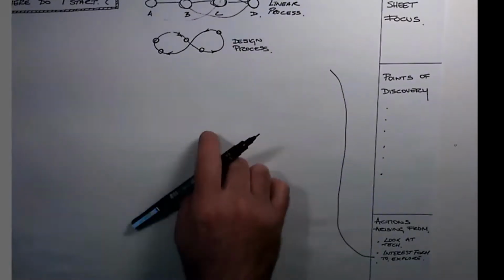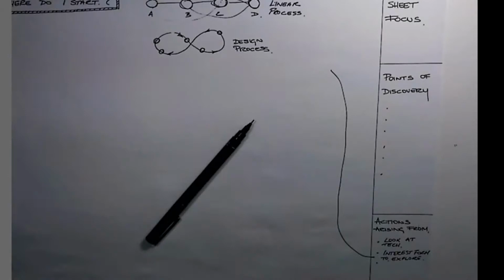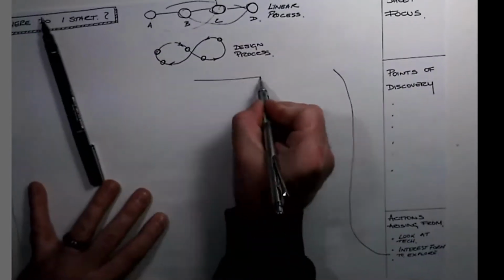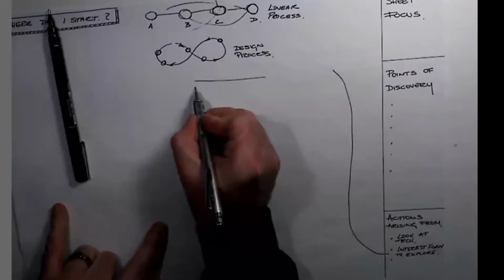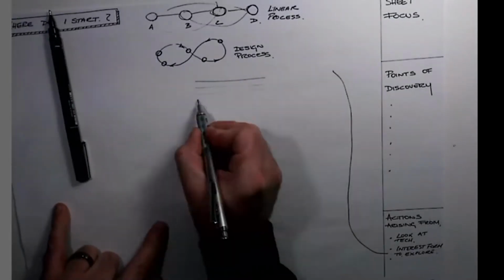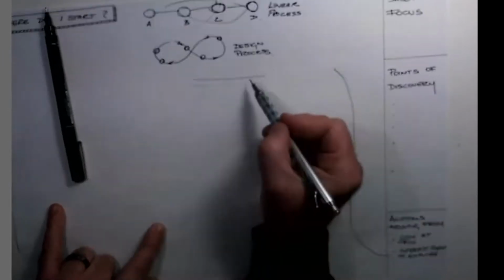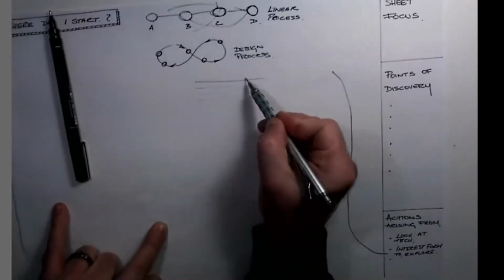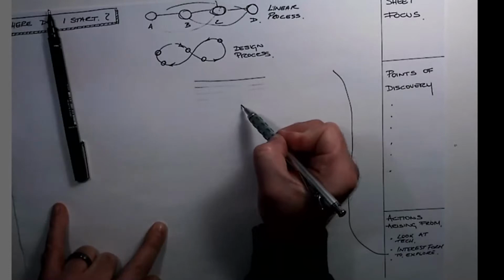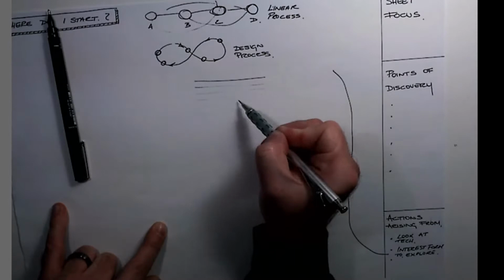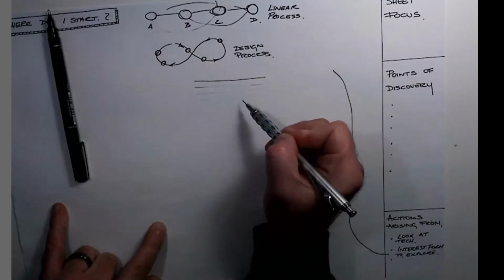Now, what I'm going to show you here this morning is, first of all, the pens. So we started off, sorry, I'm just grabbing a pencil here. We started off with sketching with pencil. And one of the beauty things about pencil is that I can vary that line weight, so that you're finding those probably tough to see. But the reality is I can vary those. So if I'm doing construction lines, they can go really, really light. But if I'm drawing outside lines, they can be dark. And that's the beauty of working with pencil.